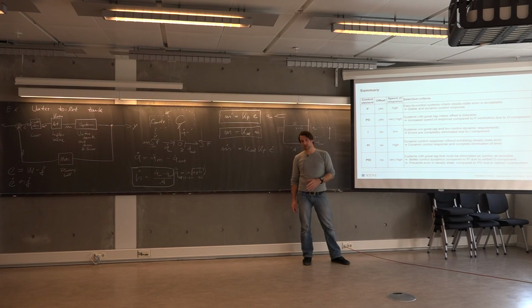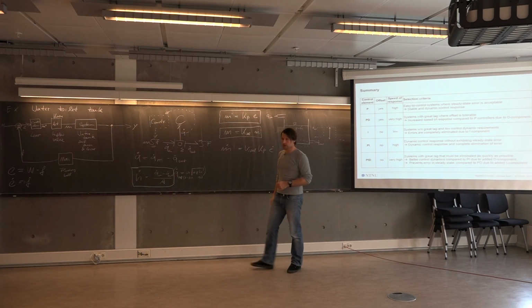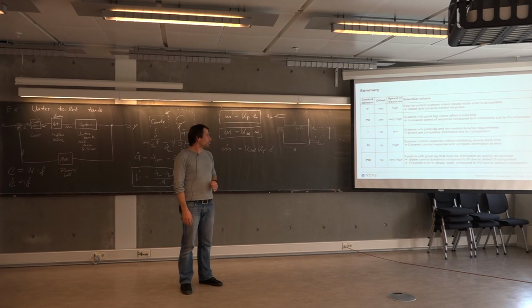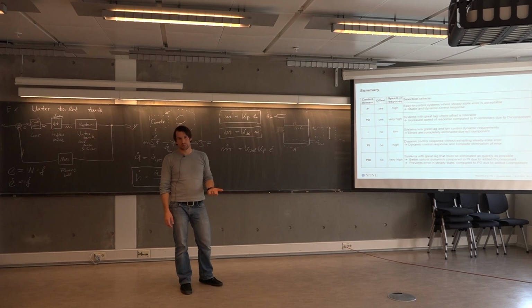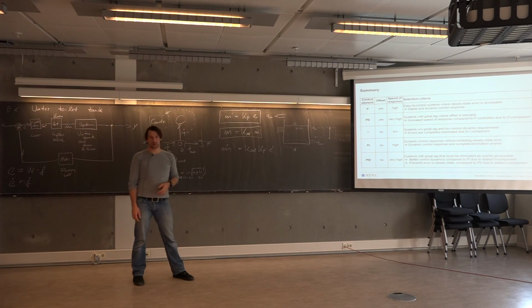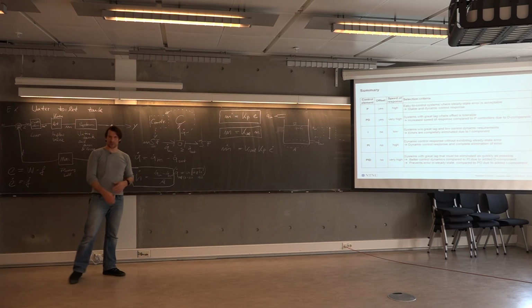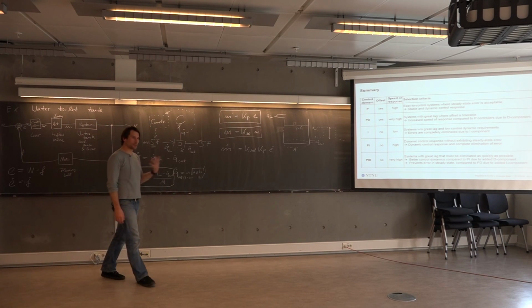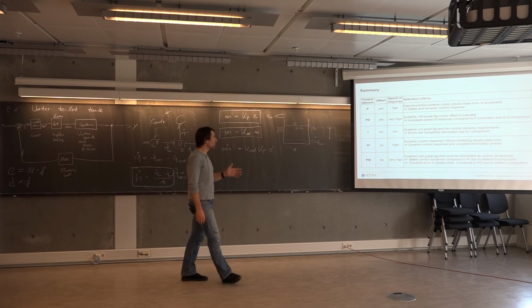You get rid of the steady state error. And this is why it is being used in most cases. But if you don't have to, because the system's behavior over time is not that important, such as with this water tank, where you don't really care about the water level height as a user, a pure P control might actually be sufficient. So it pretty much depends on the particular case which controller to choose.